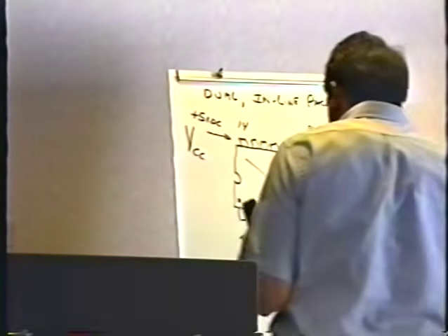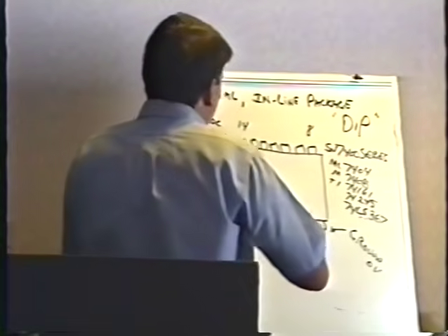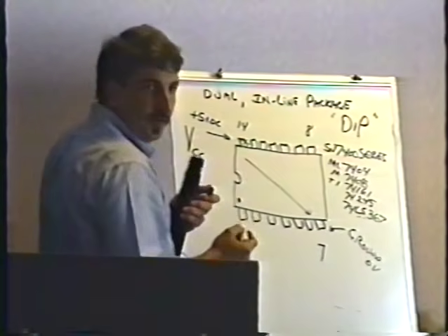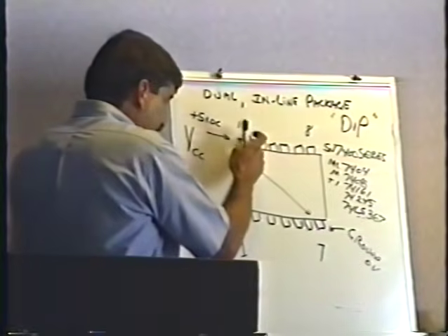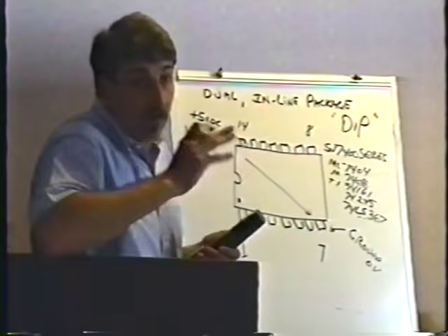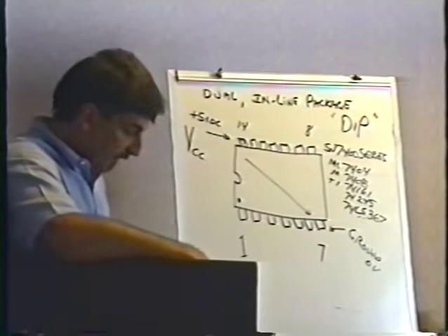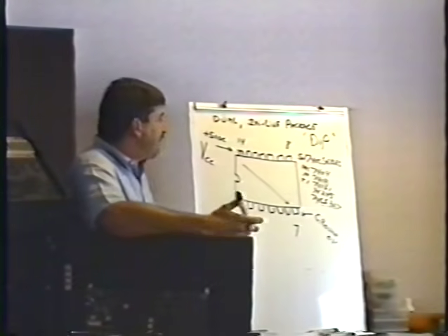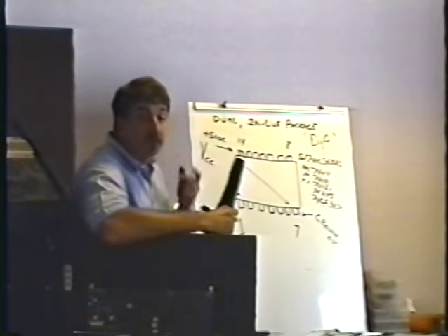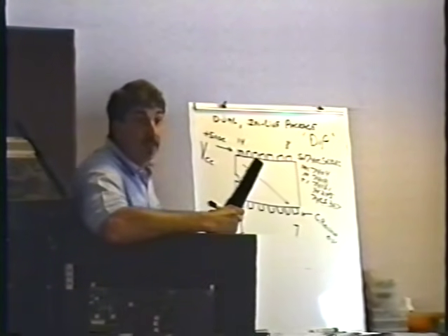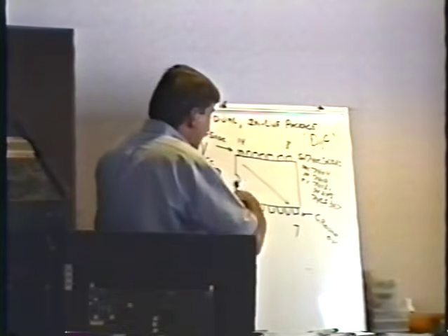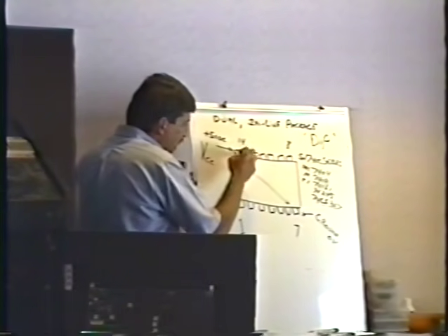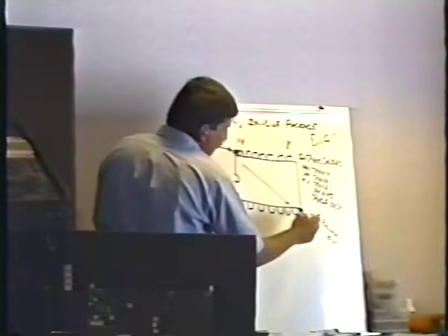So make sure you do that because the power is turned on. If you try to put the meter probe right on the top of the pin, you'll slip and short the two together. If you short 2 pins together, it probably will not damage anything, to be honest with you. These types of integrated circuits are pretty forgiving when it comes to short circuits, but you may damage something, so why take the risk? So instead, I put the red lead here, the black lead right here in the corners,